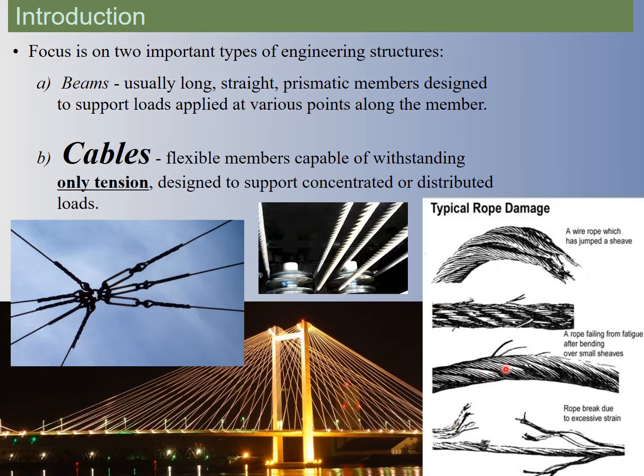So if you ever see a cable that looks frayed or is looking rusty, that's a cable that really needs to be replaced, and you don't want to be anywhere near it because when those things break and snap, they will whip around just like a rubber band that breaks. And so they're great to hold up loads, but you have to be very, very careful about the maintenance issues on these guys.